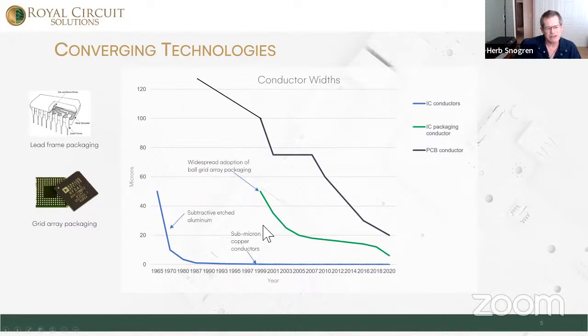The line width and space on that packaging substrate started off around 50 microns, and they were using a subtractive etch process and Microvias at the time. Then they went to the modified semi-additive process, and they were getting down to 20, 25 microns.